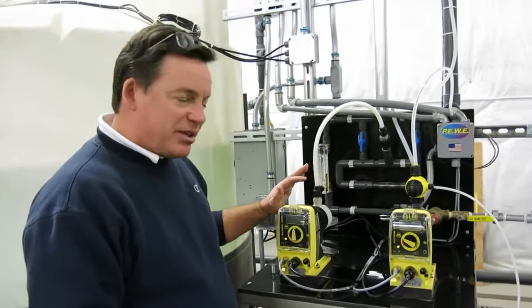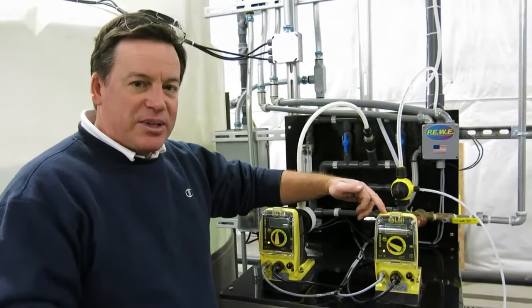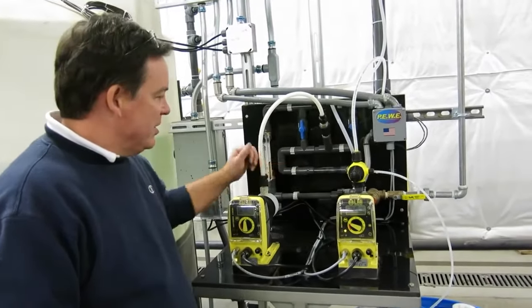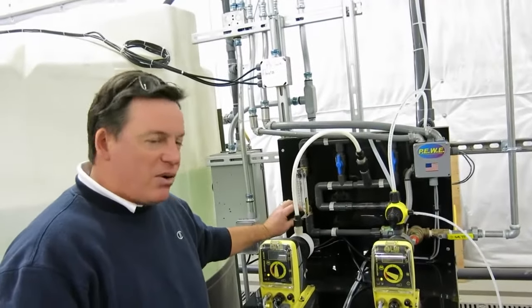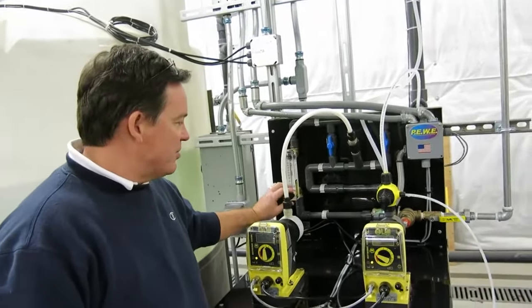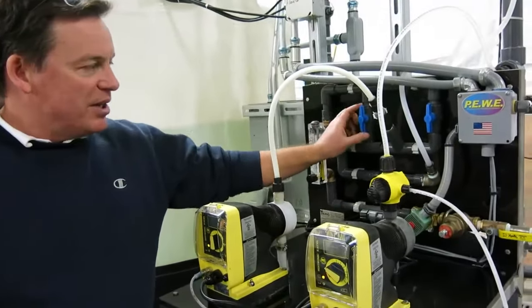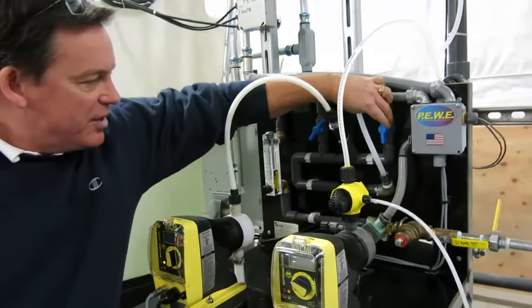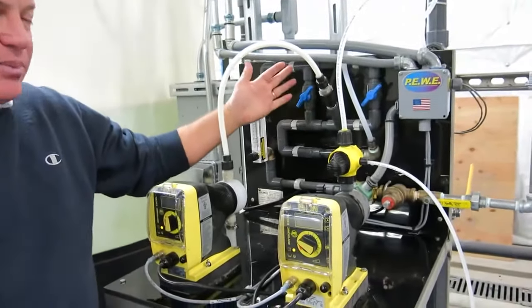So in this particular case, we have the pumps set. They're on an external feed from the command control panel. The solenoid pops open. We can regulate our flow and dilution of our polymer through this rotometer right here, and I'll set it at about 3/4 flow, and we can adjust the amount of dilution that's going through the system as it's operating. It's as simple as that.